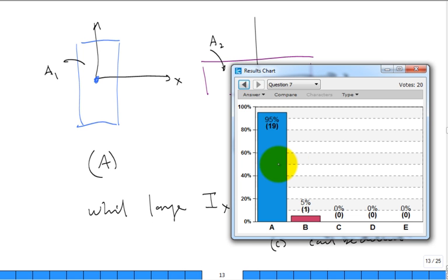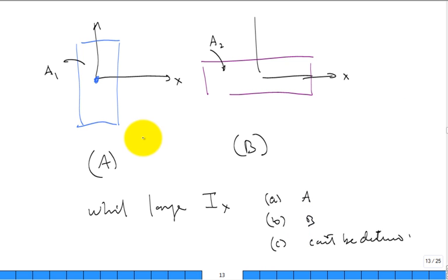And so it is A. Now why is A much larger? If you look at the equation, if I get a lot of area, this is the integral of y squared dA, if I get that chunk of area far away from the x-axis, either far away in the positive sense or far away in the negative sense, but because it's going to be squared, y squared, that leads to a larger value. Versus here, it's closer to the x-axis. It's not farther away from the x-axis. So this is larger. True.